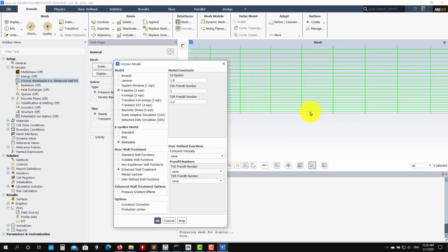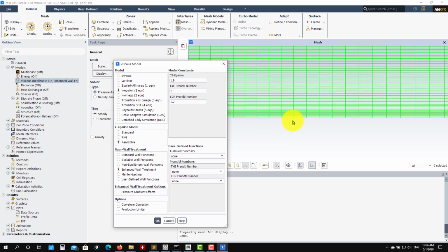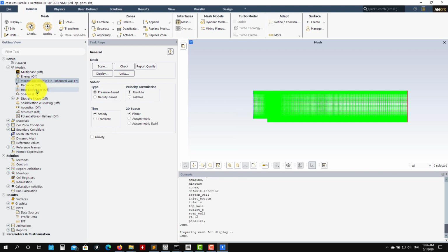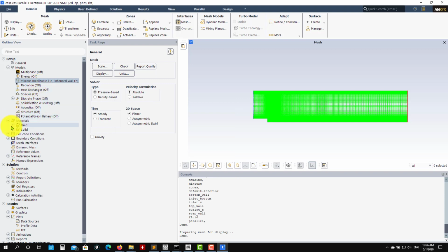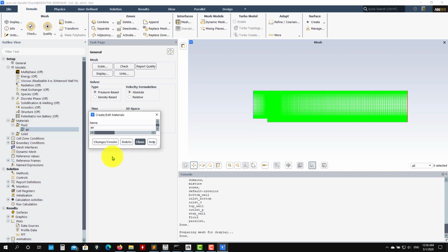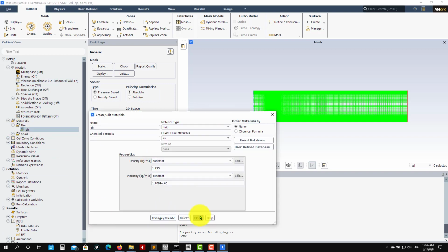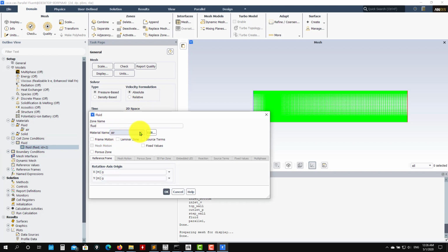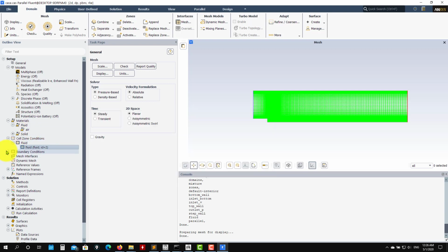See that this in theory should be a fine mesh. Okay, so let's see what we get here, as we are wall resolving. Okay, so after you choose this, nothing else in the models tab, then we go to materials. We have our working fluid, let's choose air, the standard properties. In cell zones, we go here, and remember to choose if you have different fluids or solid regions, or to add eventual sources there. So nothing to do there, defaults are okay.